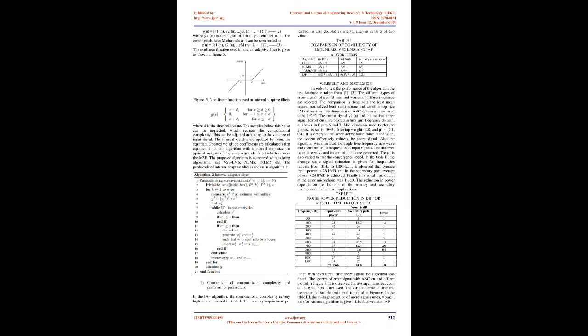2. Active noise cancellation of snore signal. In order to suppress the snore signal, an active noise cancellation (ANC) system can be used. This is an effective way to reduce the low-frequency snoring noise by using destructive interference, i.e. by superimposing a 180° phase-shifted signal, as shown in Figure 1. Figure 1: Principle of operation for an ANC system.